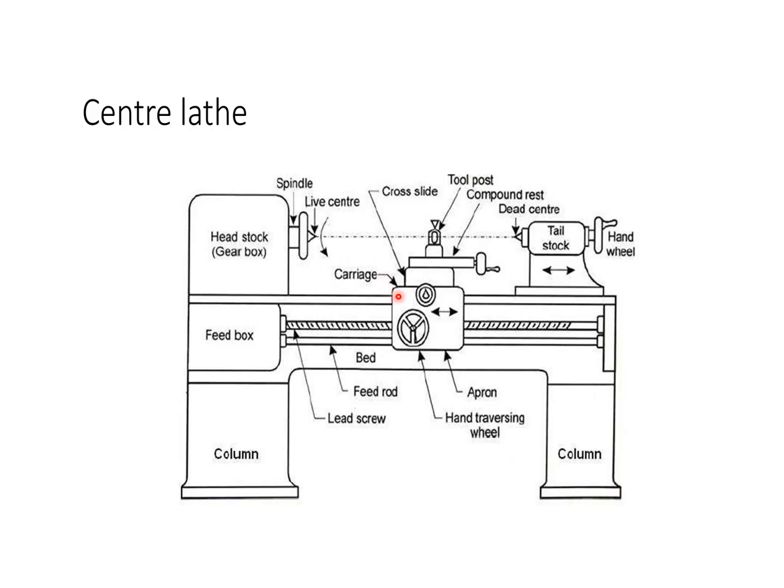The carriage is supported on the lathe bed base and can move in a direction parallel to the lathe axis. The carriage is used for giving various movements to the tool by hand and by power. It carries saddle, cross slide, compound rest, tool post, and apron.